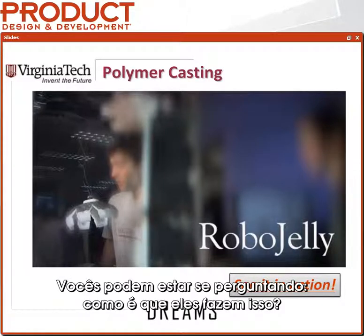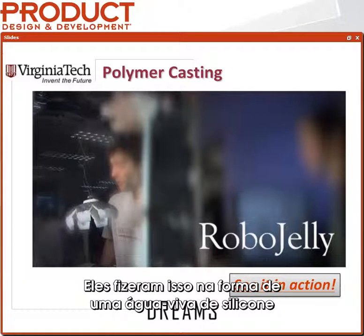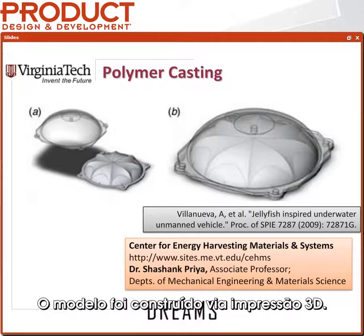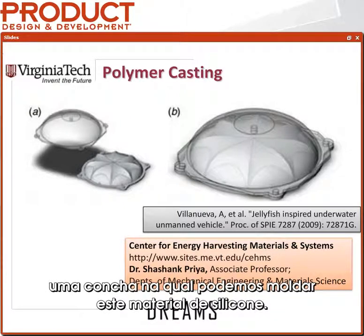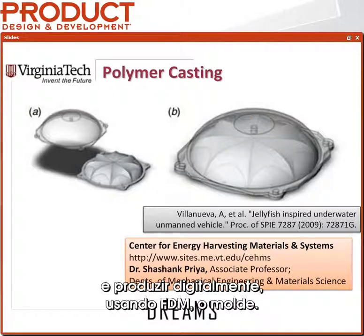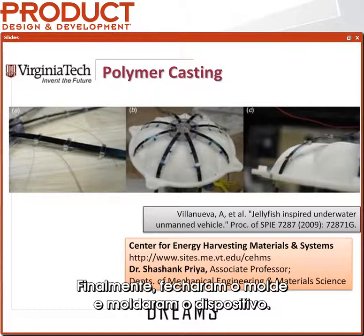So you might ask yourself, how in the heck do they make that? So I'll invite you to come back to our presentation. The way in which they made that, a silicone jellyfish with embedded shape memory actuation, was actually through 3D printing. Using an FDM printer, we printed a shell into which we can then cast this silicone material. So they were able to digitally design and then fabricate that mold using FDM. They then lay in their shape memory alloy and the spring steel, and then close that mold and cast the device.